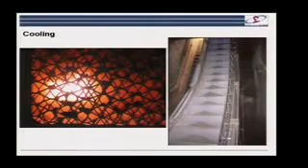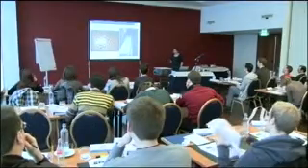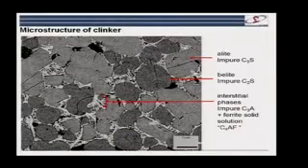That's the clinker coming out. You see this is the grid that's used to cool it. You have air coming through here. You see these are the nodules of clinker, which is typically up to 1 centimeter in size, and then they go on to this thing here where they're allowed to cool down. Still very hot at this point. And if you cut one of those nodules open and look inside it, this is what you see.